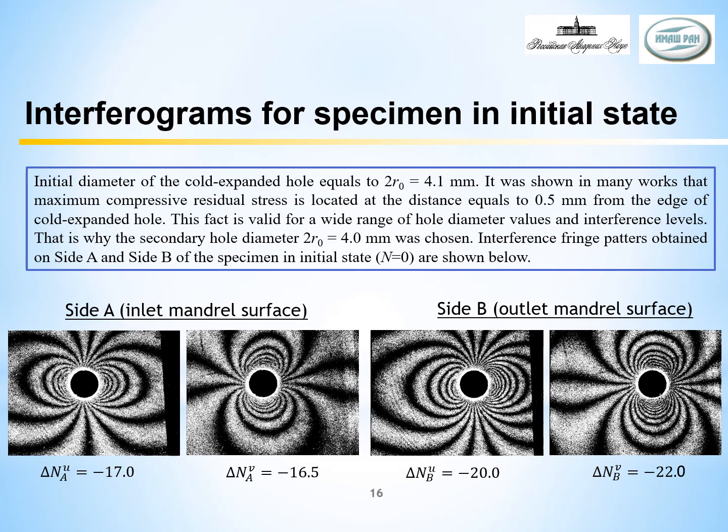This interferogram demonstrates the very high quality of the technology that is used for the cold expansion process. It should also be noted that the deformation response revealed on side B, the outlet mandrel surface, exceeds the similar parameter on side A, corresponding to the inlet mandrel surface.